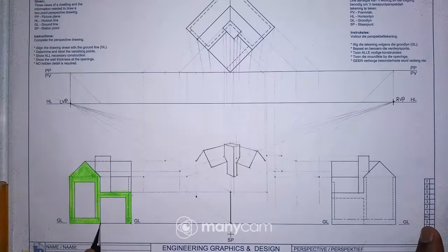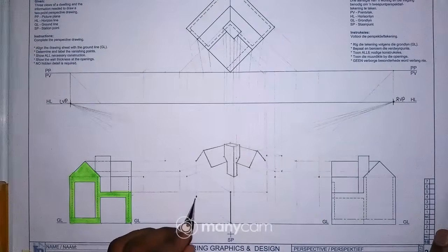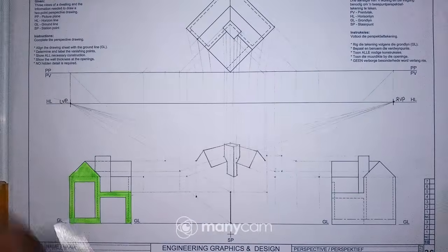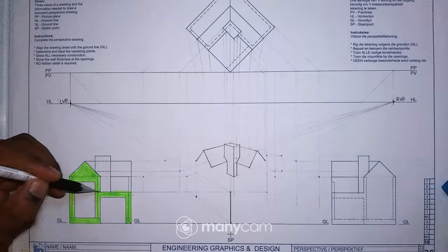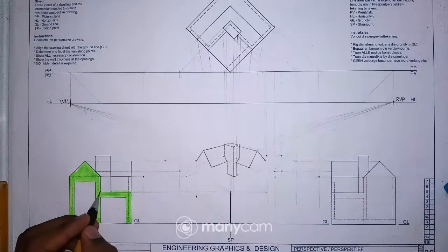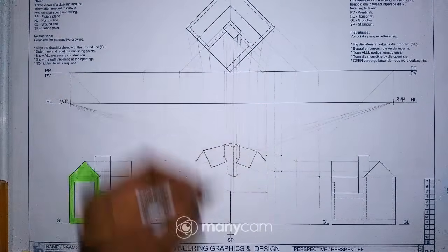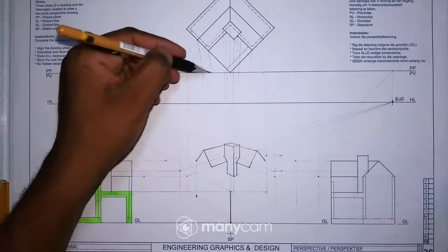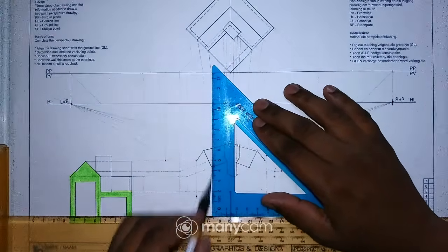Why? Because if you check this surface, or these 2 points, or this opening here, I have something there. Because if it's an opening, I can't have an outline there, so I will just leave it as it is for now, like this. And then because I have this point, let me try and get this point now. This point, where is it from the top? That point is right there. So I have to take this point to the station point first, and then I draw a vertical line. So that line is just right there.